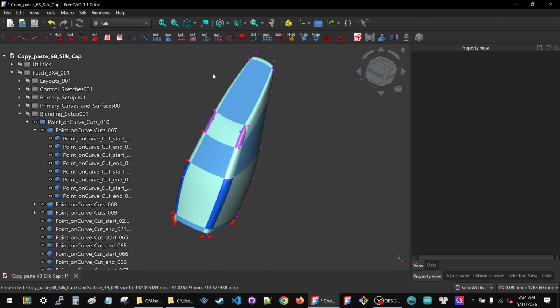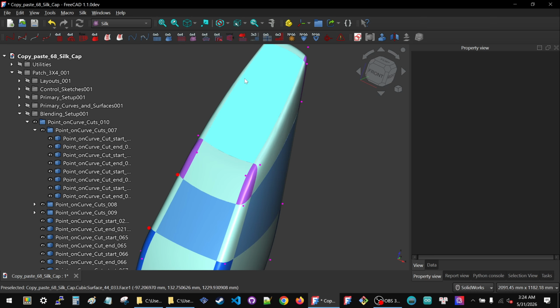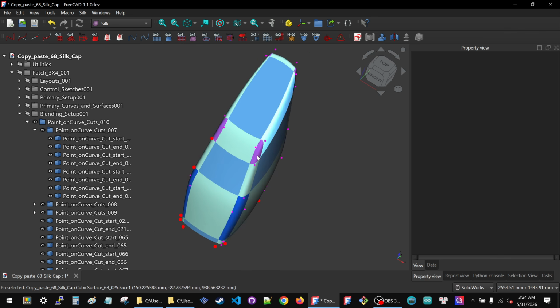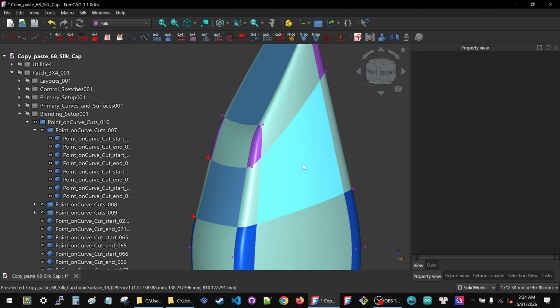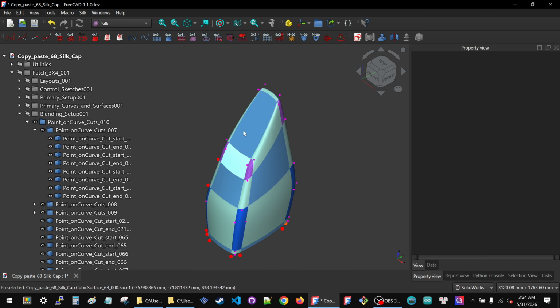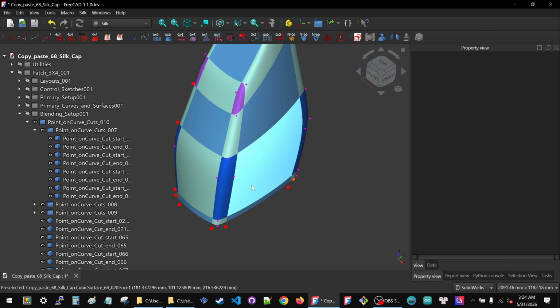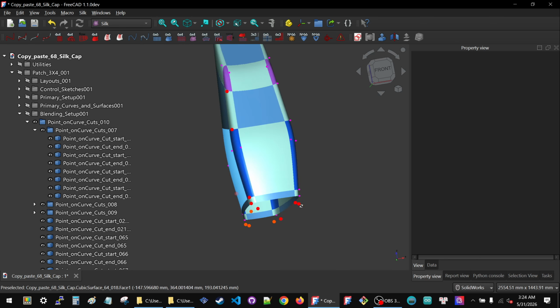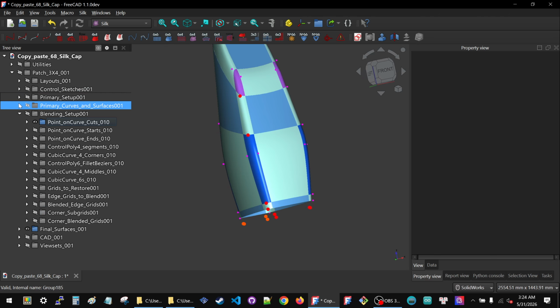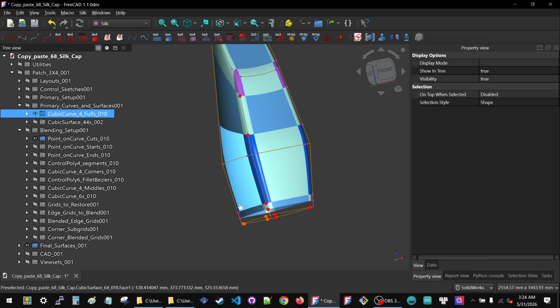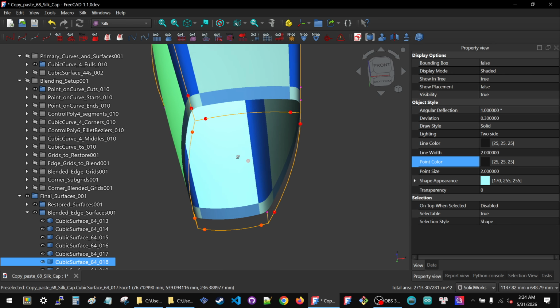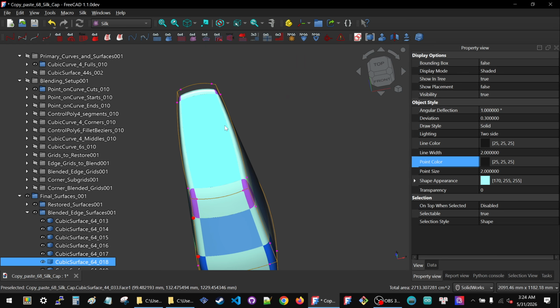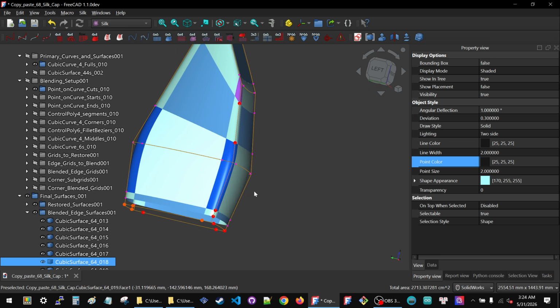So because we have a single face across the top, we're not using a standard CAD trick to fill this. We are literally using silk to blend across this non-standard topology. So I'm going to flag those differently. You see now, how many totally free points do I have available to control these cuts? Well, now I only have 4 for the bottom section because this bottom section is a face of its own. So it forces left to right alignment and top to bottom alignment. And I still have 4 cutting points along the length of the loft.